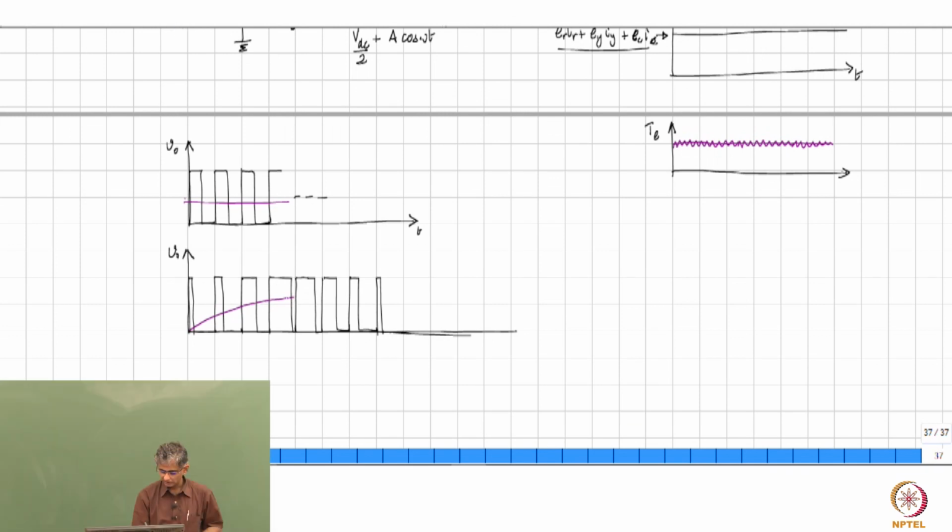So now the average goes down and goes towards 0, right? So now what we are doing is we are generating a sinusoidal moving average. As you move the window along, you find that the average defined over one cycle of switching is varying along this x-axis, and that variation can be made to define a sinusoid.